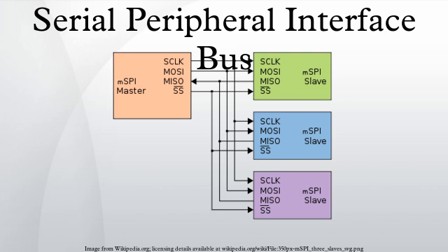Clock polarity and phase. In addition to setting the clock frequency, the master must also configure the clock polarity and phase with respect to the data. Freescale's SPI block guide names these two options CPOL and CPHA respectively, and most vendors have adopted that convention. The timing diagram is shown to the right. The timing is further described below and applies to both the master and the slave device.